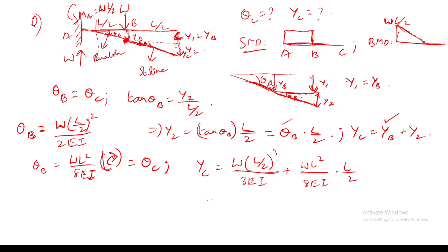Then you will get yc. What is the value of yc? 5wL cube upon 48EI in the downward direction.